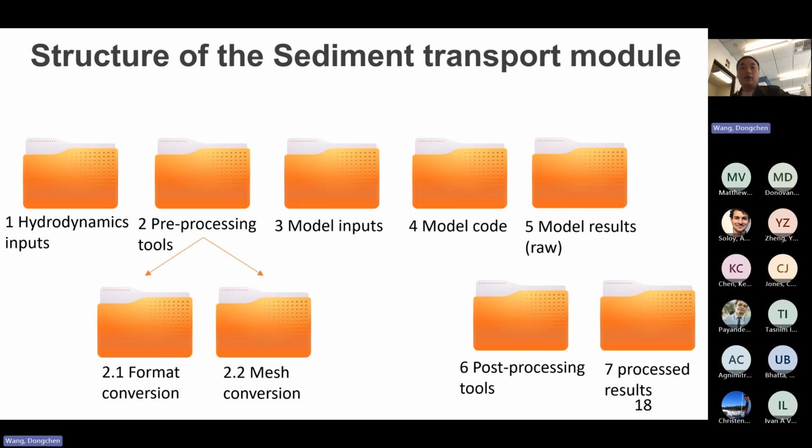The water sample is also taken at the same location and brought back to the lab, where the grains are chemically processed, and the floc aggregates are broken in this process. Then we measure these individual grain sizes. We use these two distributions to calculate information about the flocs.